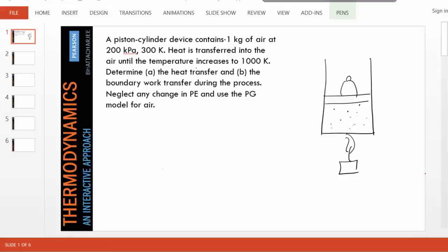a free body diagram of the piston, you can see, again, this we have done in chapter 0, we have a force of the weight on top and atmospheric pressure pushing it down, and the gas from inside pushing it up. So even though the piston moves because of heating, it is not accelerating, so there is no net force on the piston. As a result, you can show that because the outside forces, the forces downwards, are never changing, these are all the same forces, the inside pressure must be constant. In fact, you can figure out exactly how much weight to place so that the pressure inside is 200 kPa. To do an experiment like that, you can figure the weight out and put that on the piston.